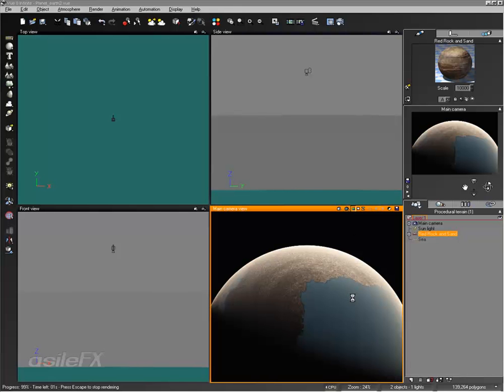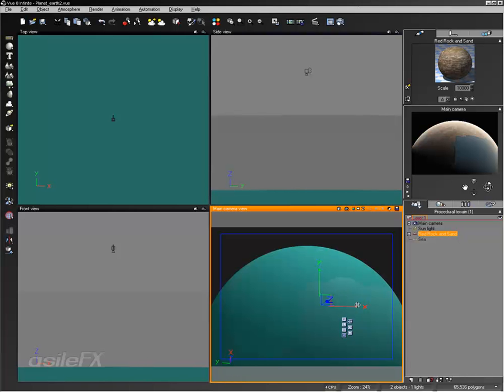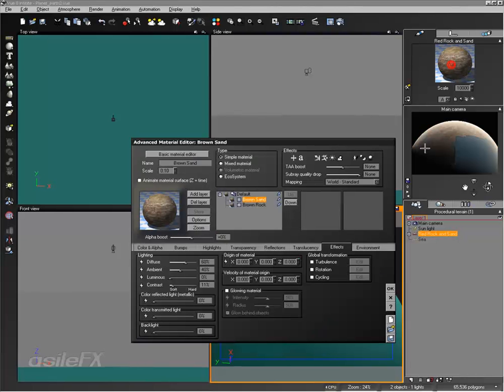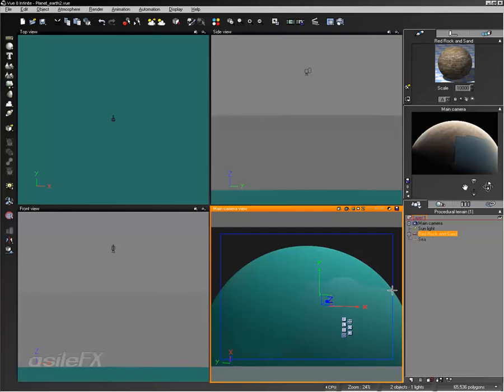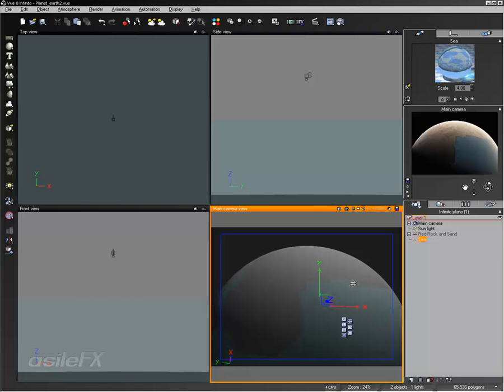And you'll probably need to make a few adjustments and tweaks to the image offset or latitude longitude of the planetary map to get it to match a color map, which you would have to use the object parametric mode to wrap around. One cool thing you can do is also use planetary maps to distribute mixed materials in order to give a much better variation overall. And this even allows you to use the sea object to add coastal foam if you want. So there's a lot of control you have.